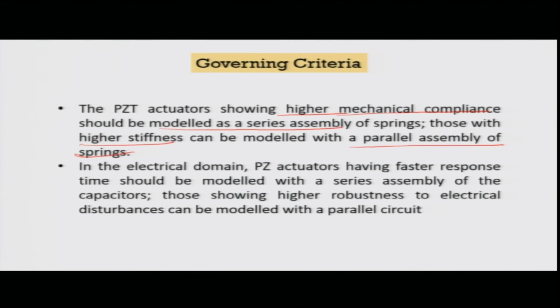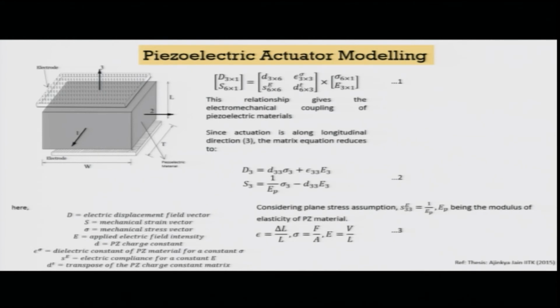In the electrical domain, piezoelectric actuators having faster response time should be modeled with a series assembly of capacitors, and for higher robustness should be modeled with a parallel circuit. So, this is the final governing criteria that we are talking about. If you model such a piezoelectric element, in this case we made a 2-port model, the top part is the electric field displacement, and this is the strain, and here is the stress and the electric field that you are applying to the system.